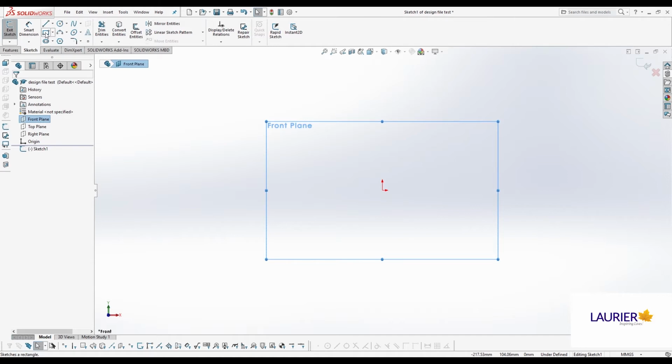And where do we want to locate it? Of course, we will always want to start any rectangular object so that the origin is at the lower left of the rectangular object. For a circular object, we always want to put the origin in the middle. And this is just a standard that's used in drafting so that we always know where the 0 is on our drawing. While this isn't strictly necessary to make things work here in the CAD world, in the CNC world, it is important if we're going to draw something later on that we want to impact with this object from somewhere else in space. If we don't know exactly where this object is, when we bring another object towards it to impact with it and become part of it, it's not going to hit where we think it's going to hit. It's always good to have these reference points, and that's why they build them right into the CAD.